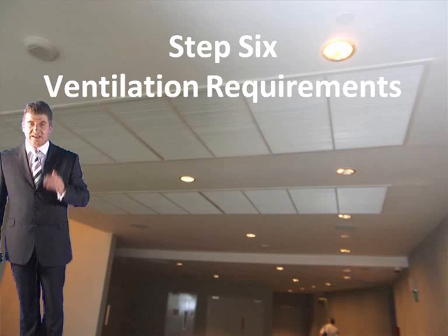Well, in this case, clearly, stratification is very unlikely to occur. So you've proven it's not going to stratify. The smoke should make it to the ventilators. So let's move on to step 6 now, which is determining the ventilation requirements.